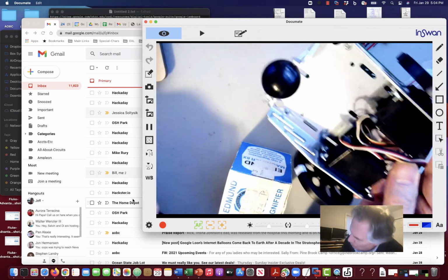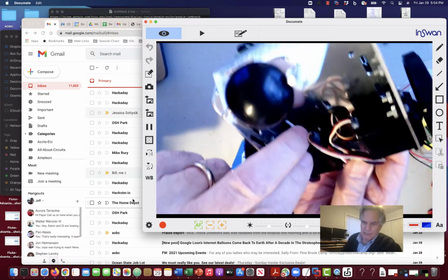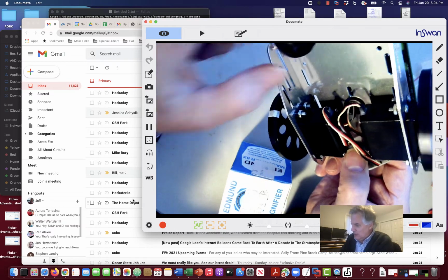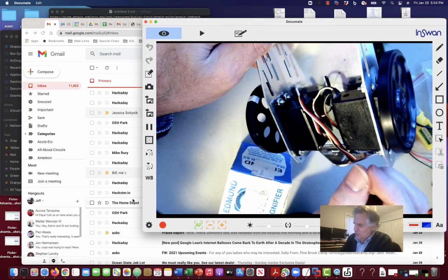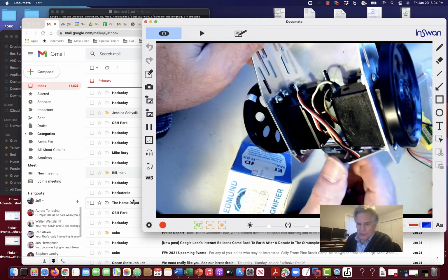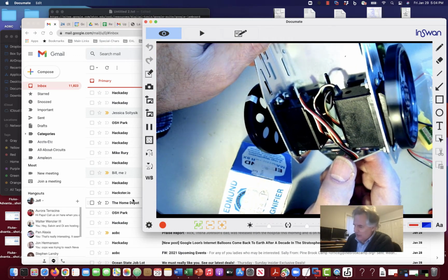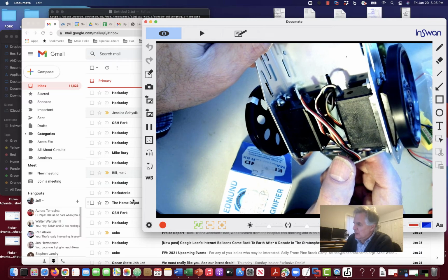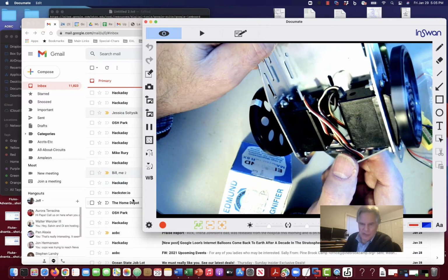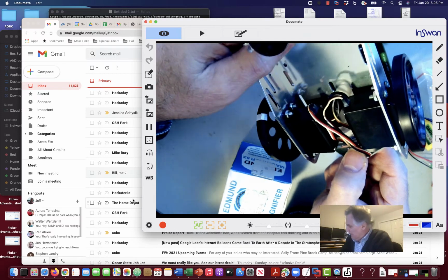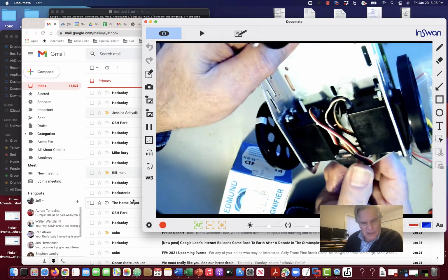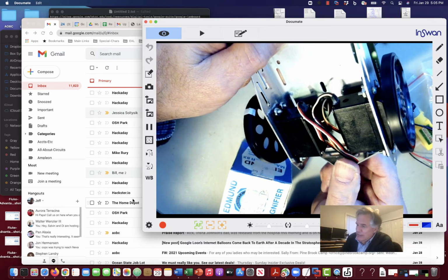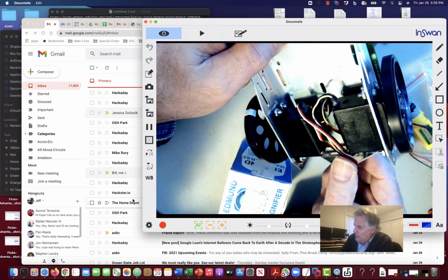And there's a place in these things, unfortunately you can't really see it, but you might remember it. There's a place where you can stick in your screwdriver and tune these so that they're both going about the same speed when they're both given 750, and so on. So I think maybe they're supposed to go a speed of 0 at 750. And then they go faster when you use the larger numbers like 1200 in one direction, and they go faster in numbers less than 750 in the other direction, like 300.